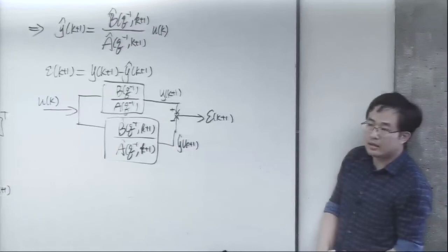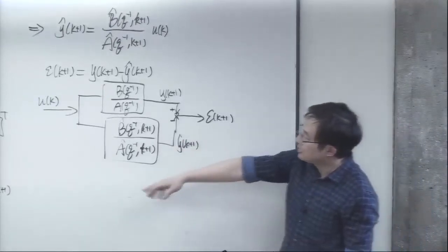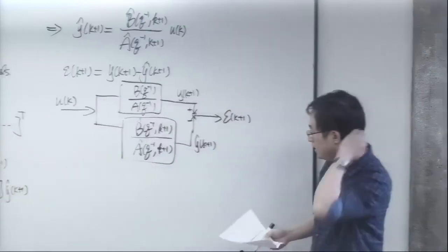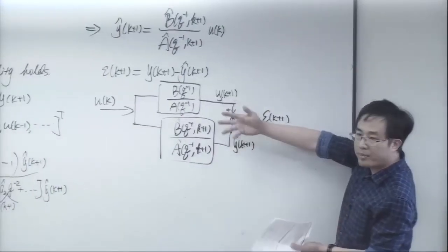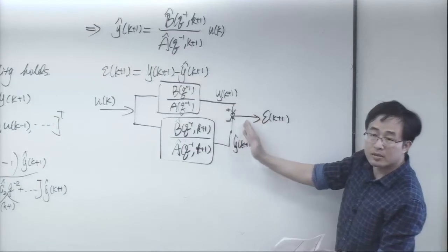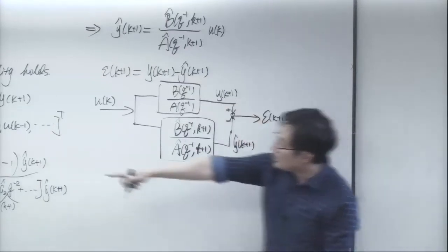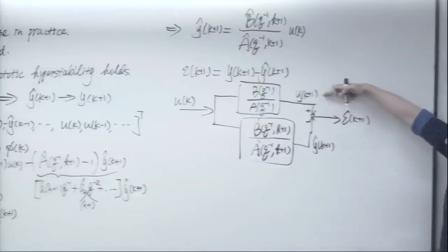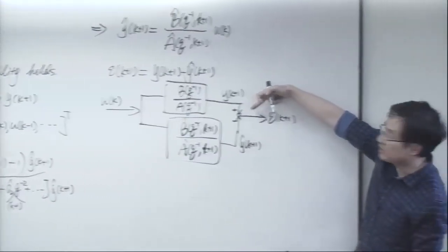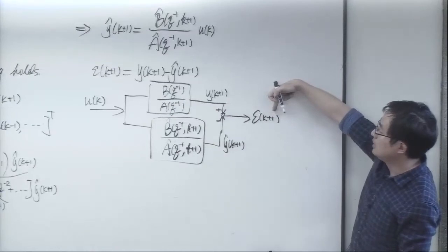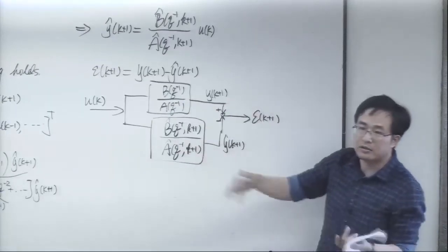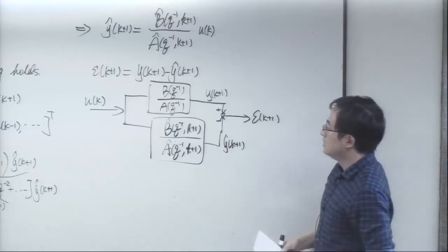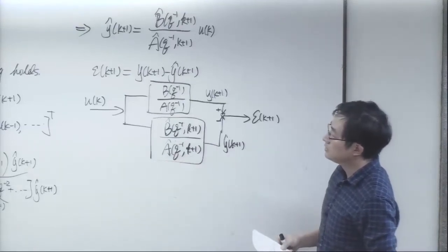And in this way, you see the subtle difference in the regressor construction actually leads to a more parallel structure. If you think about it from the noise perspective again, over there, noise in y is going to go through A hat. Now in here, if this contains noise, it goes straight to here, instead of being filtered again by some complex operation in A hat.